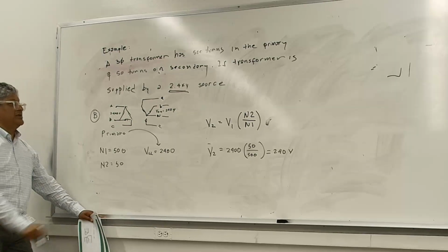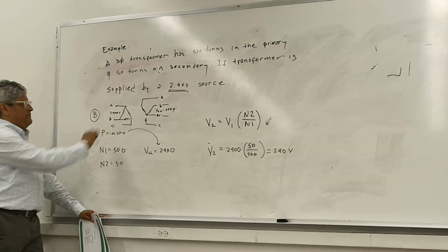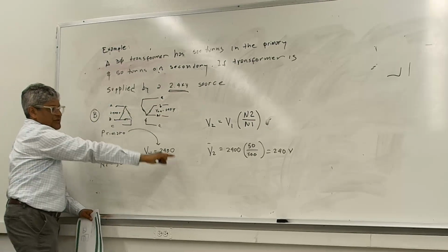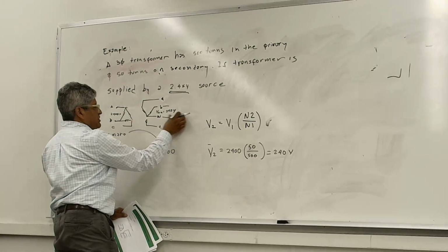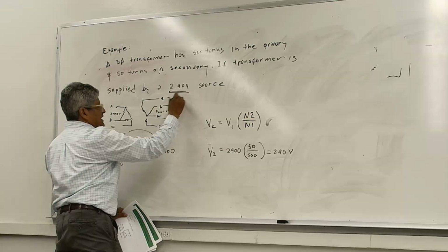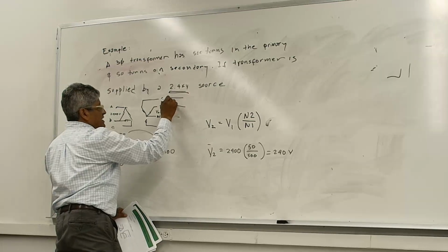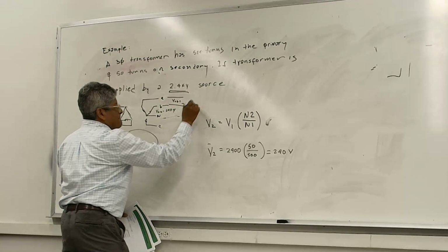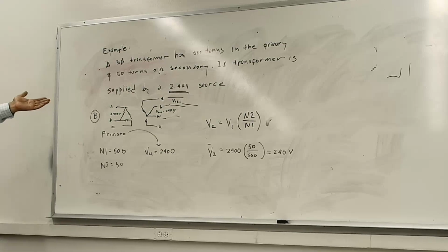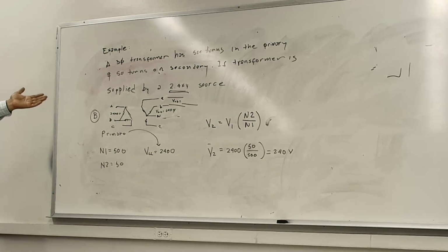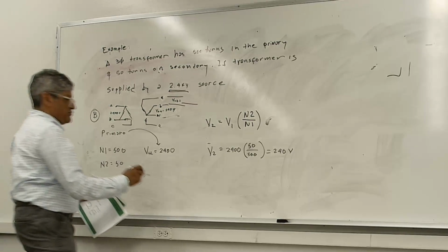Just purely magnitude. Okay, because I'm coupling this, I have 240 volts on the secondary. How do I get my voltages now from the line to line, from VAB? Root 3 times that. Exactly. So I just take the voltage on that winding on the secondary, line to neutral, and I multiply by the square root of 3, and that's how I get my line to line voltage, right?